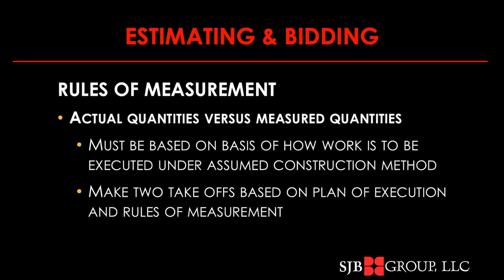An example of that is the standard specifications for DOTD projects say they'll pay for the excavation for a footing, and that's equal to the size of the footing plus 2 foot around the footing. Whereas your work approach might be, if the hole is more than 5 foot deep, now you've got OSHA considerations, you're going to have to sheet the hole.